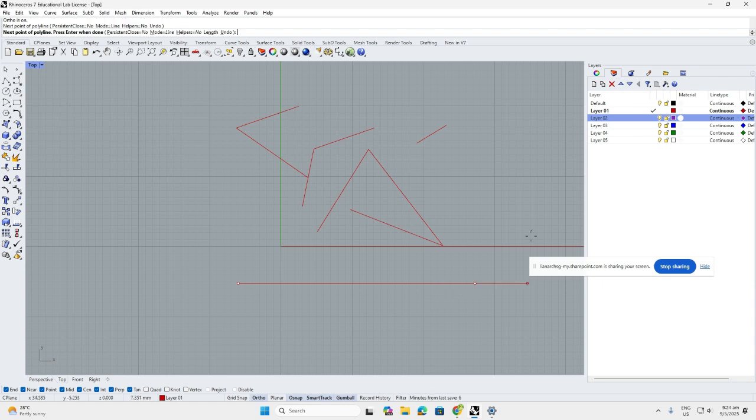Okay. You can also, when you have this particular direction fixed, you can press tab to make sure that it will not stray off, and you can then lock to a particular element that you want. For example, to this part. This is very good for alignment. So just to repeat, use the tab button and it will lock to any other portion that you would like to have. For example, here. So you will lock here, and then you can click here again.